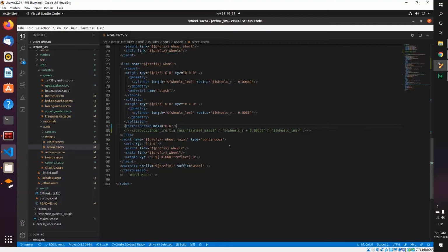So the three things that you need to verify about your model sinking are the transmissions. Please disable them and run the demo to see if everything is over the ground. You have to adjust the PID controls and also the inertia of the model. If the inertia is too low, probably this will cause something odd with Gazebo. But basically it's about the PID, the weights, and the inertias when you associate the transmission tag to the motor.